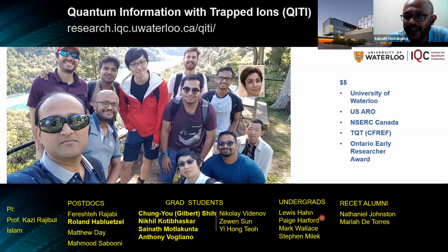So we have huge conductance and big pumps, and we are not using any materials inside that have higher outgassing. So it's basically the choice of pumps, good conductivity of components, and choosing materials such that we hope to achieve the best pressures. And this new pre-baking recipe would also reduce the hydrogen gas load.